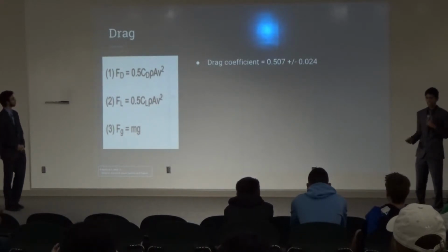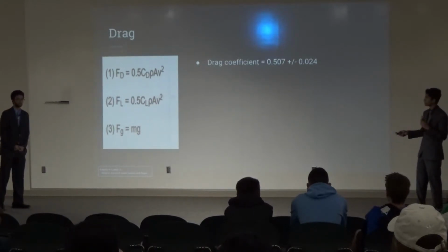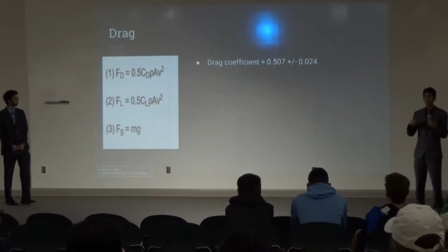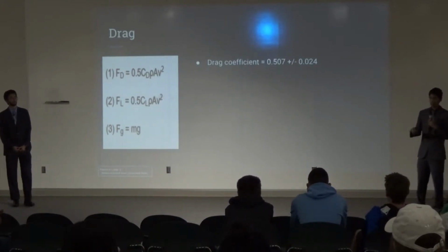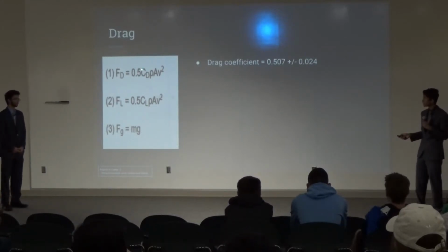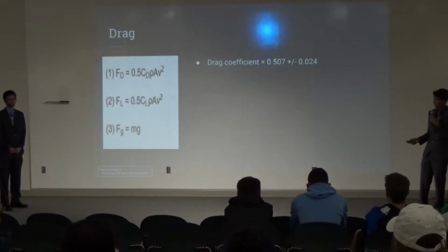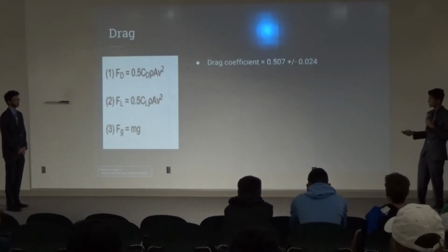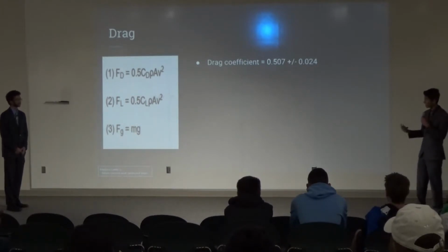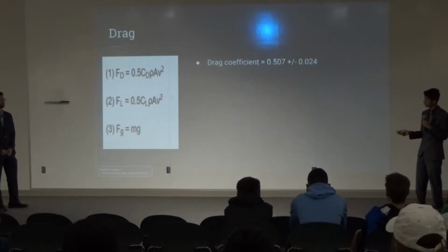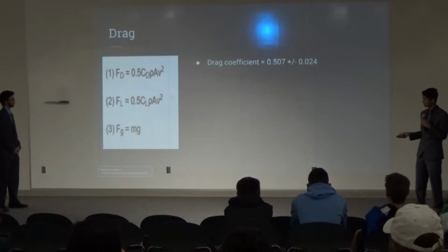Additionally, if you guys know this equation, it looks kind of complicated, but it really isn't. The 0.5 is just a half when you convert forces into energy. The second is the coefficient of drag, which is just a number that shows what the influence of the force will actually be on the ball. And that's just something we determine through lab analysis. The thing that looks like a P is actually the Greek letter rho, and that is supposed to demonstrate the density of the medium that it's flying through. So in this case, the density of air. The A is the cross-sectional area of the object that's moving and the drag force acting upon. And v squared is the velocity of it, so that's what the equation is.